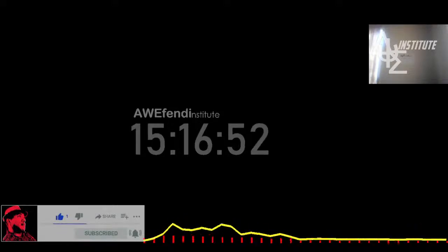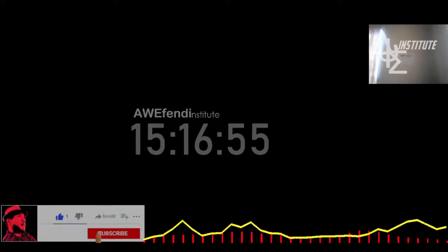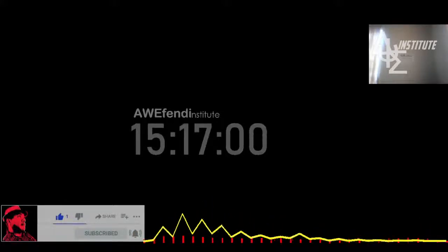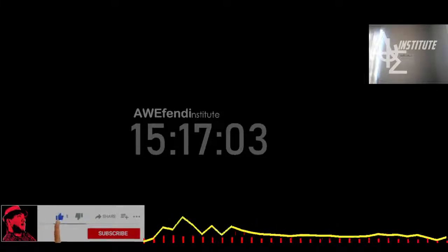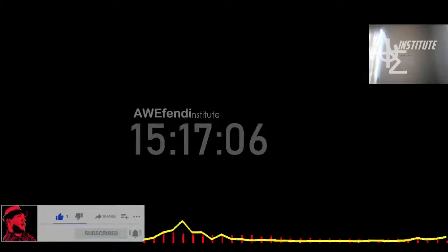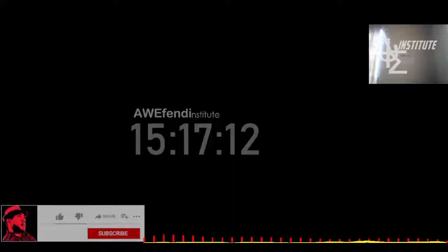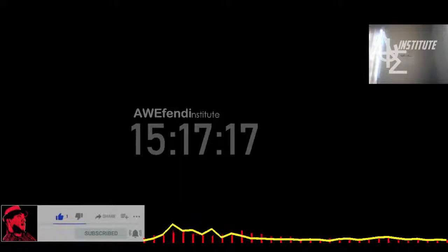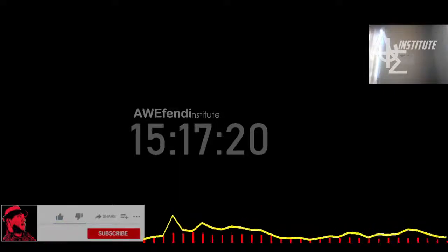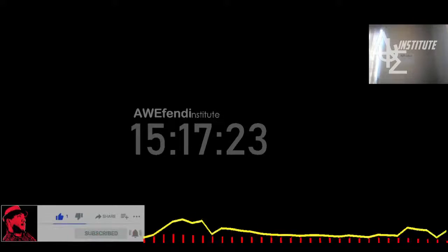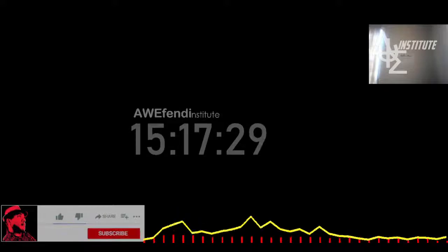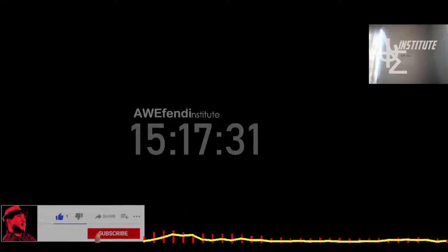You can actually also show maximum and minimum locations. So maximum's up here on the IGBT, minimum is somewhere down here, or in the fluid flow itself, probably close to the inlet. And then on the bottom here, you can see we have much cooler IGBTs. So the efficiency of this cooling channel is probably not as uniform as it should be. You could probably consider redesigning it so that you have maybe a couple more zigzag channels passing underneath this upper IGBT to cool it down a bit more and get it a little bit closer to the temperatures on the bottom. So that's some kind of design variation that you might want to consider.